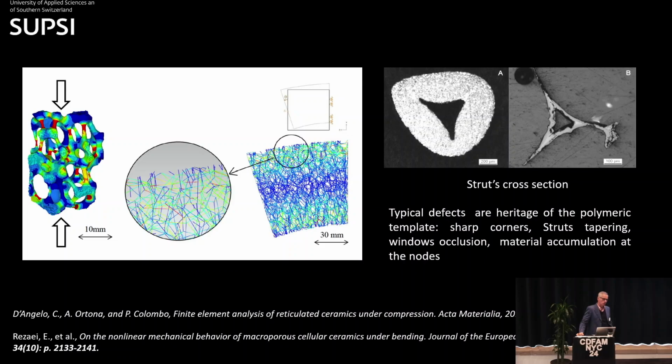It's very interesting to see from where we started. We were trying to understand how this really random structure, and by random I mean really random, because it's a foaming process you cannot control in the end, behaves. We were trying to understand which were the weakest points of these structures and so forth. And so we started doing computer tomography of the foams we were making, applying some loading, which could be thermal, mechanical, whatever, and we were watching where this material is able to fail first.